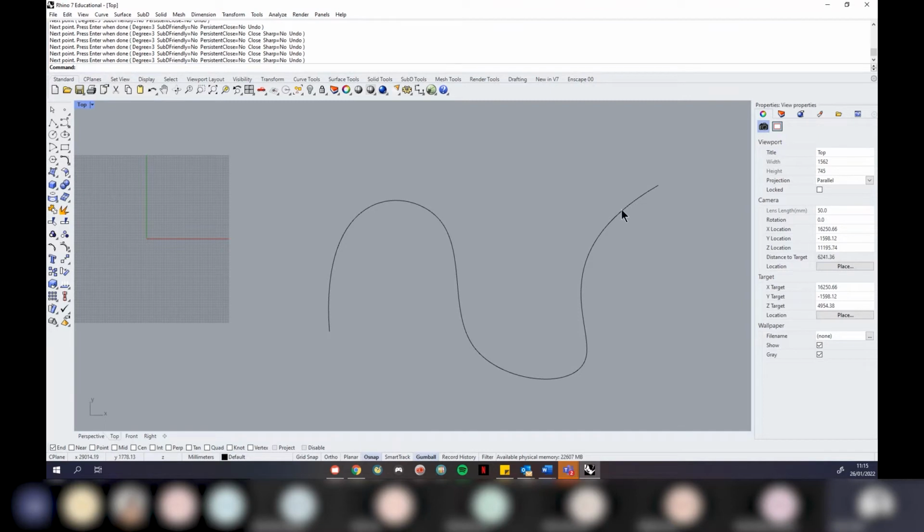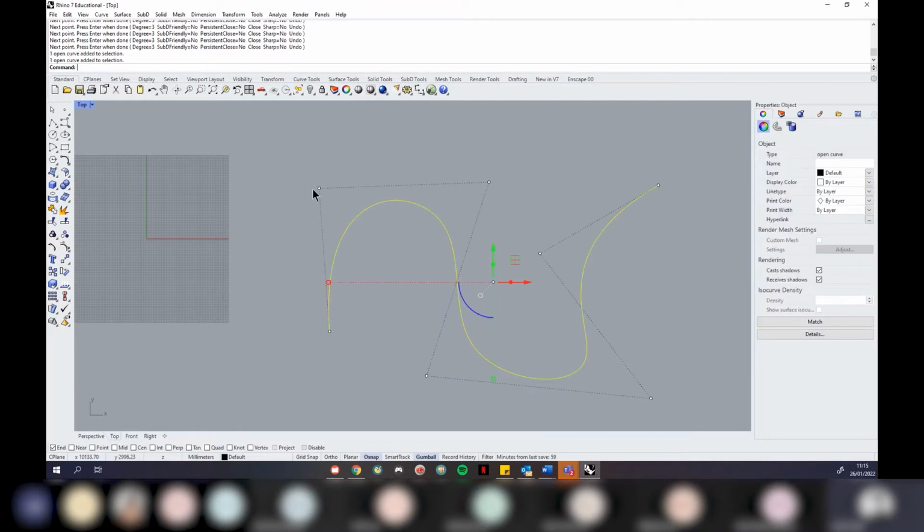It's worth mentioning as well that when you want to finish a curve, you want to hit enter. Don't hit escape like you would in CAD. Hit enter to finish it. Now, with the standard control point curve, you see where we've placed the points, and you kind of see what it's doing. It's using these points as anchors, so it's going to loosely fit between those points. Some of you are going to really like that. Some of you are going to hate it.